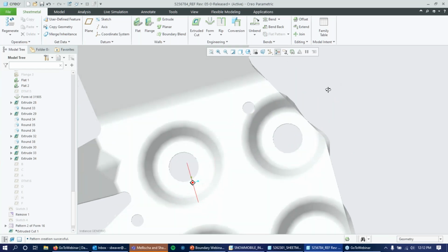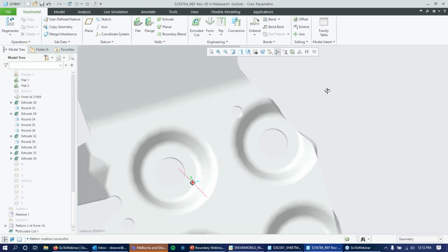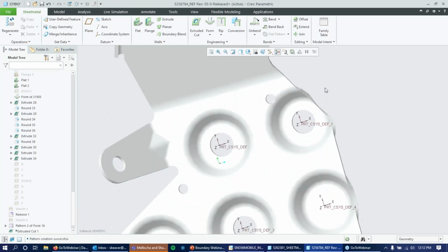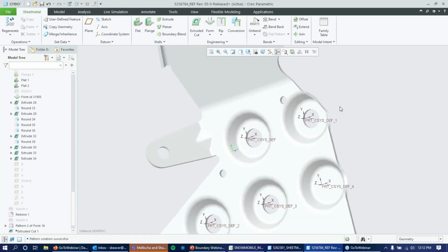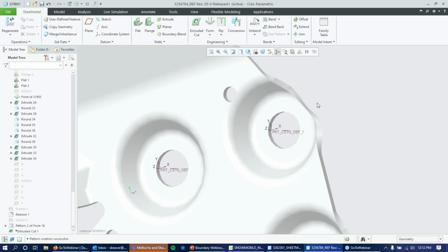And these punch forms are extending to the edge of my sheet metal. But we can see that these edges where it intersects are going to be curved. And they're actually going to be calculated based on starting with a flat sheet of sheet metal. So I think this is just a really, really good example of first of all, seeing how these calculations are done, how Creo is looking at this and calculating how this material is going to bend, so the directions and dimensions in every direction you're going to encounter.